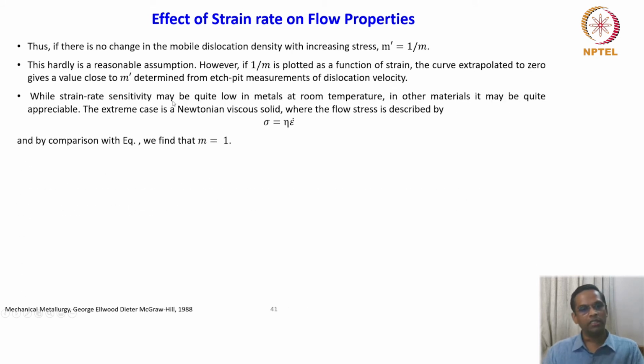While strain rate sensitivity may be quite low in metals at room temperature, in other materials it may be quite appreciable. The extreme case is a Newtonian viscous solid where the flow stress is described by sigma is equal to eta times epsilon dot.